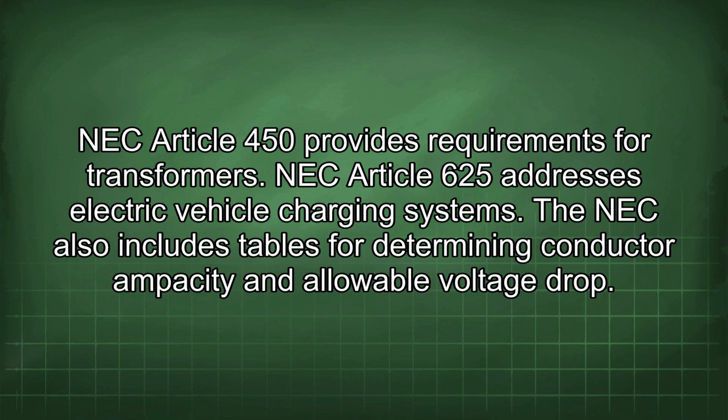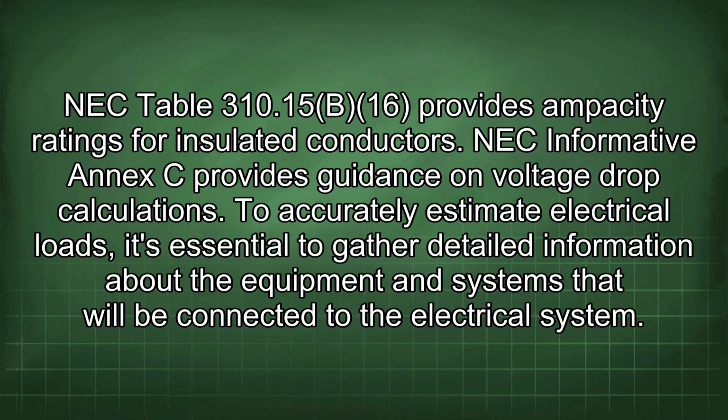The NEC also includes tables for determining conductor ampacity and allowable voltage drop. NEC Table 310.15(B)(16) provides ampacity ratings for insulated conductors. NEC Informative Annex C provides guidance on voltage drop calculations.